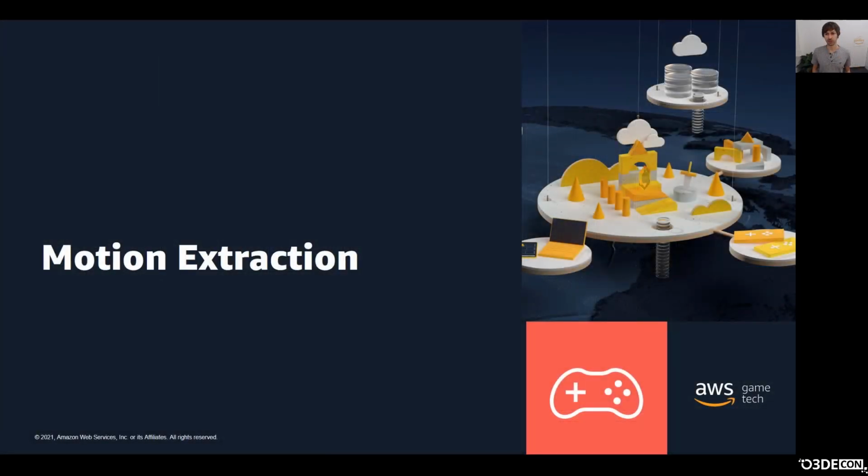There is one last thing that I want to talk about before bringing our character into a level. Let's talk about motion extraction. Motion extraction is the process that, in case the animation is moving the character and thus moving the root joint along the space, takes the motion of the root node away from the root joint and applies it to the character capsule. In case of playing a walk animation, rather than resetting the character position back to the origin with each loop, motion extraction keeps the character smoothly walking forward.